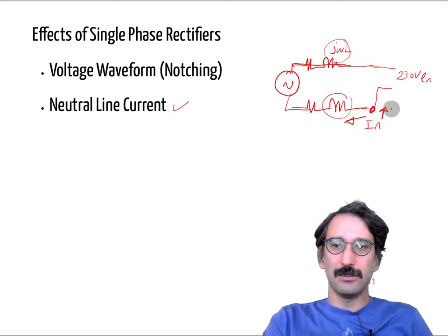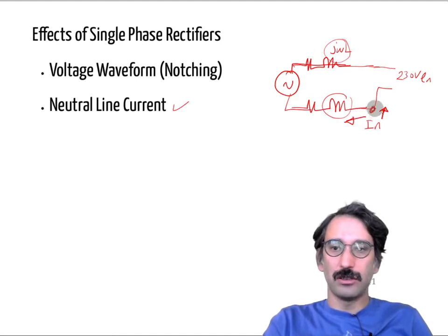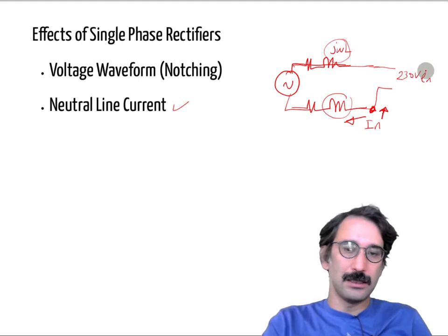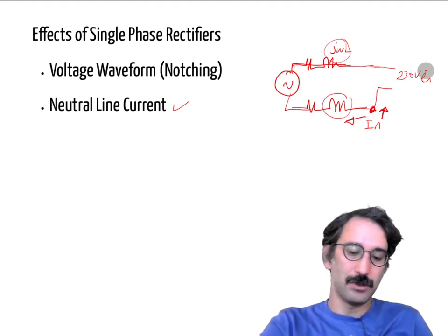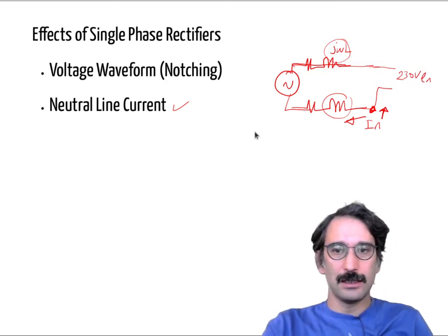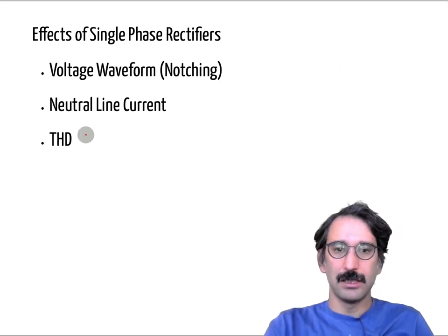So you will not have 0 volts, but you will have a higher point voltage at that point, even if you are using balanced current, and that can create some problems in safety, both for you and also for your equipment. And next you will have the THD problems.